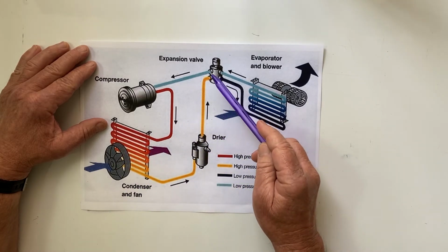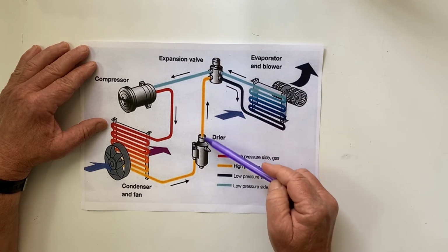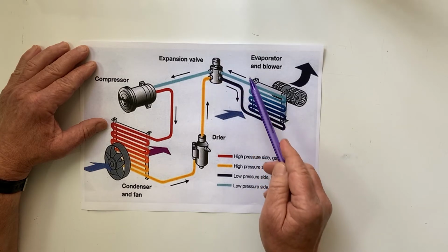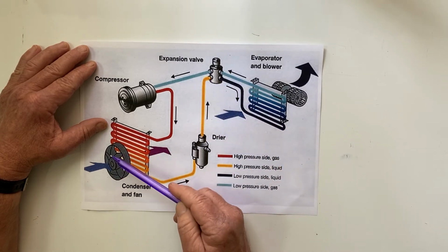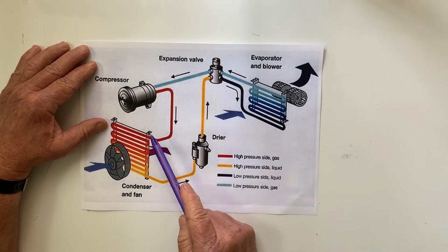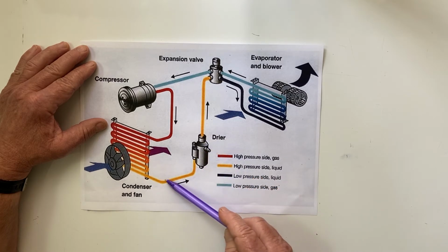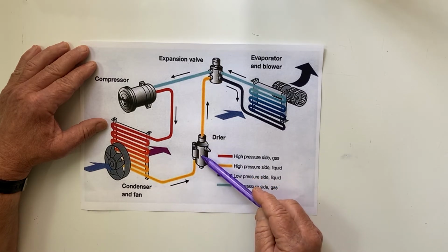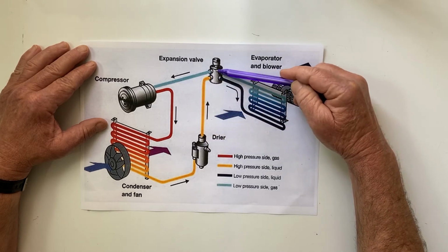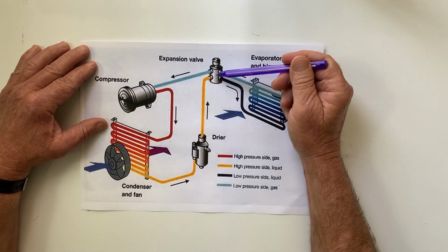the expansion valve, realistically, there's a lot of different designs. This one has the receiver dryer, the refrigerant making its way into the expansion valve, but also the returning refrigerant passing through it as well. They don't all have that design, but this is probably becoming one of the most popular. Now, the liquid that comes out through and into the receiver dryer then makes its way up through to an orifice, and that orifice is called the thermal expansion valve for good reason.